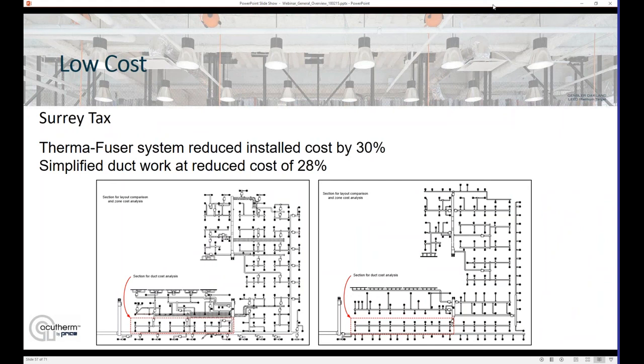I mentioned earlier the costs of the low-pressure ductwork can be a little bit more, but that's not always the case. It really depends on the orientation and layout of the building, just the geometries of the building. In some cases, and that's why I throw this example in, the ductwork can get a little bit less expensive, not because it's smaller, but because you can simplify it just by reducing the number of transitions, elbows, and connections. So there are options there as well when it comes to the cost to have some savings in the ductwork.